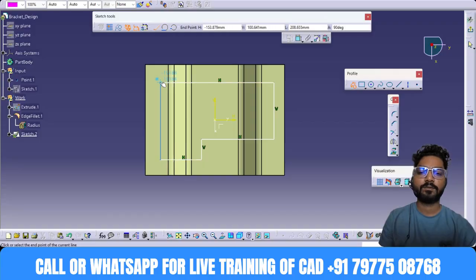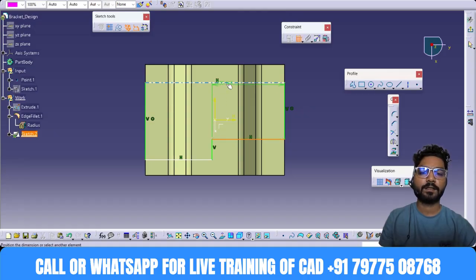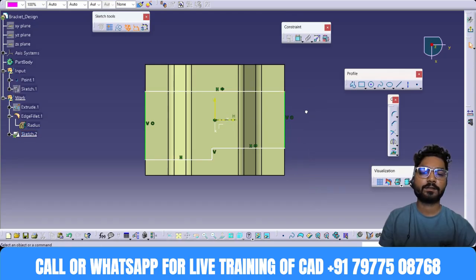That shape I want to cut from the bracket's lower surface. Now this and this will be coincident, then this and this coincident, then this line and this line make a symmetry, and then this line and this line I'll make coincident.